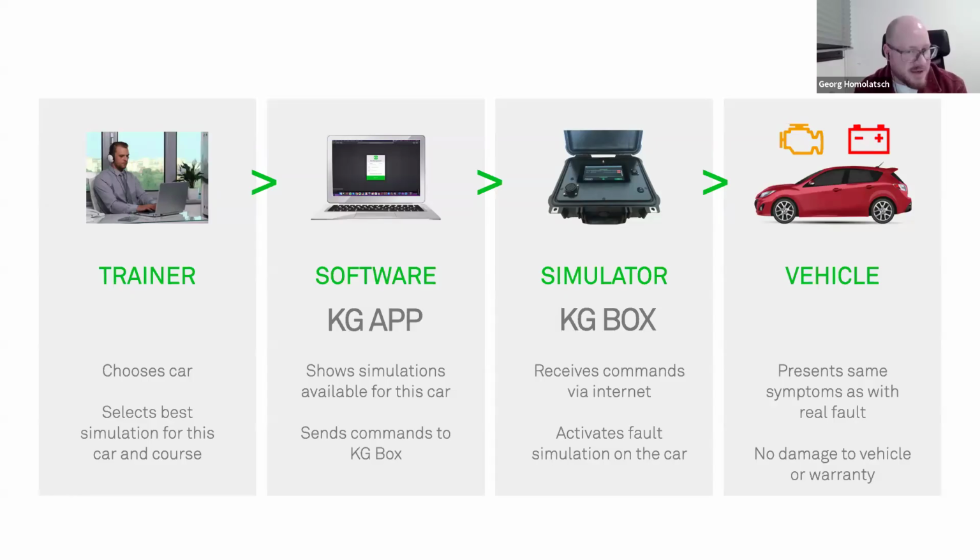And then in the third step, taking measurements with a multimeter or oscilloscope and interpreting these measurements, comparing them to manufacturer values, and then in the last step, going over to saying, okay, this hypothesis was correct, and this initial hypothesis was incorrect. So our goal here is really to create a realistic and secure environment where the learner can go through all steps of the diagnostic process on a real vehicle, right?